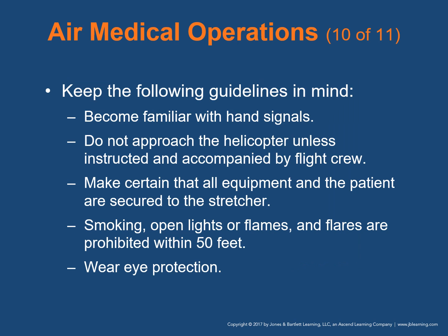Keep the following guidelines in mind when operating in a landing zone. Become familiar with your jurisdiction's helicopter hand signals. Do not approach the helicopter unless instructed and accompanied by flight crew. Make certain that all patient care equipment and patient are properly secured to the structure. Some helicopters may load patients from the side, where others have a rear landing door. It just depends on the aircraft configuration. Any smoking, open flames, and flares are prohibited within 50 feet of the aircraft at all times. Do wear eye protection during approach and takeoff.